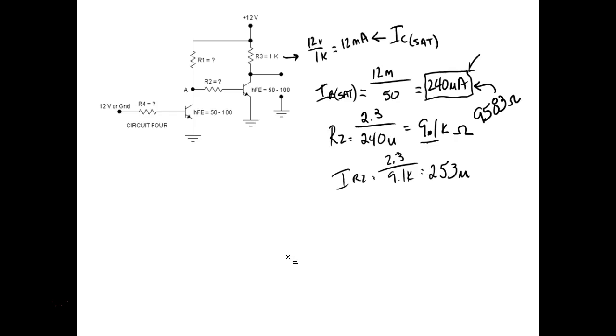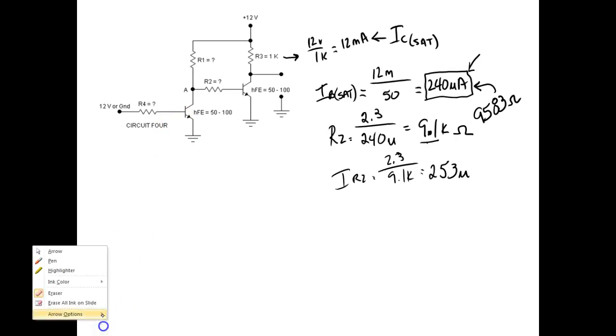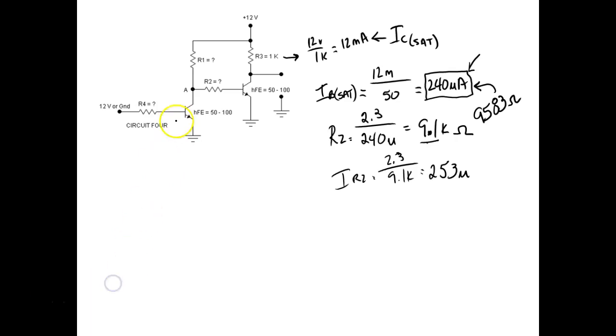And this is where I think my worksheet runs into a little problem. Oh, okay, this flows when this guy here turns off. So what we have now is we're calculating the size of this resistor. So I got 3 volts right there, right? Y'all understand? So you were right. If 3 volts is dropped there, this transistor is what? Off.